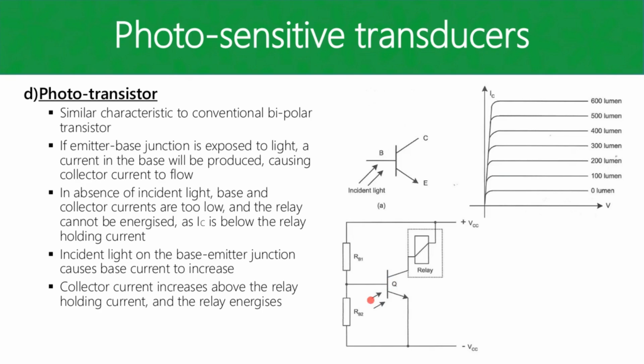In actual fact, they don't really look like that. Phototransistors are essentially just something like this with the base exposed to light. That's the way it actually operates. This layout, this component also exists, but it kind of defeats the purpose, having a base connection. You do get this, but it's not used often. This configuration of the phototransistor is actually used more.